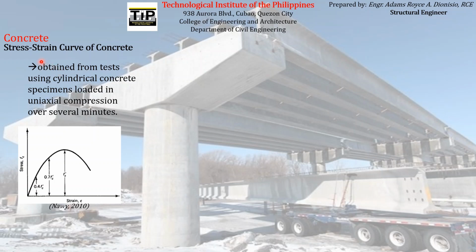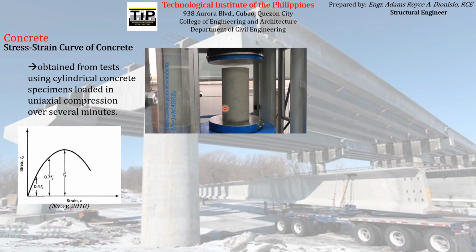The stress-strain curve of concrete is obtained from tests using cylindrical concrete specimens loaded in uniaxial compression over several minutes, just like what I have shown before. This is again the concrete cylinder specified by ASTM with dimensions of 6-inch diameter or 150 mm by 12-inch height or 300 mm.